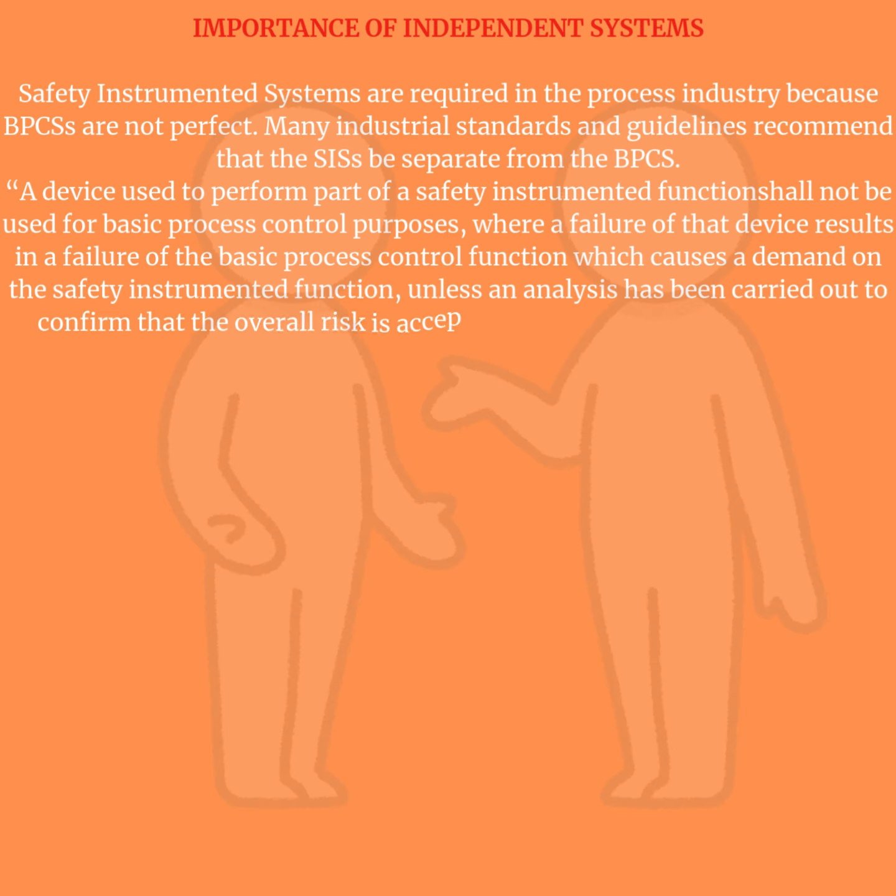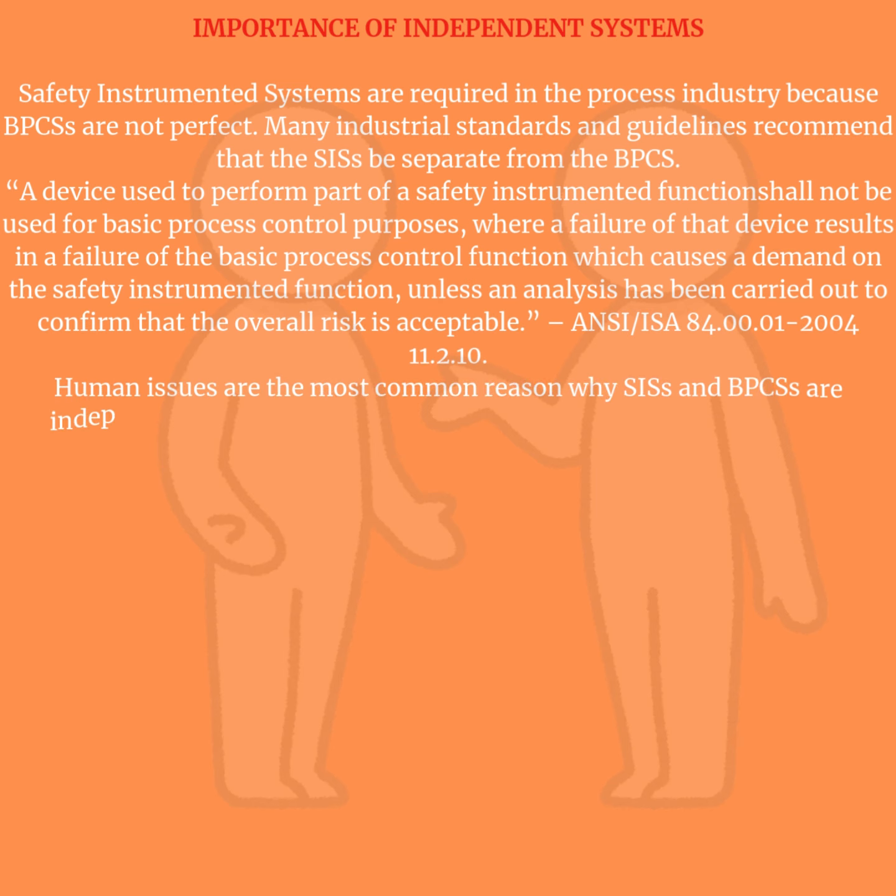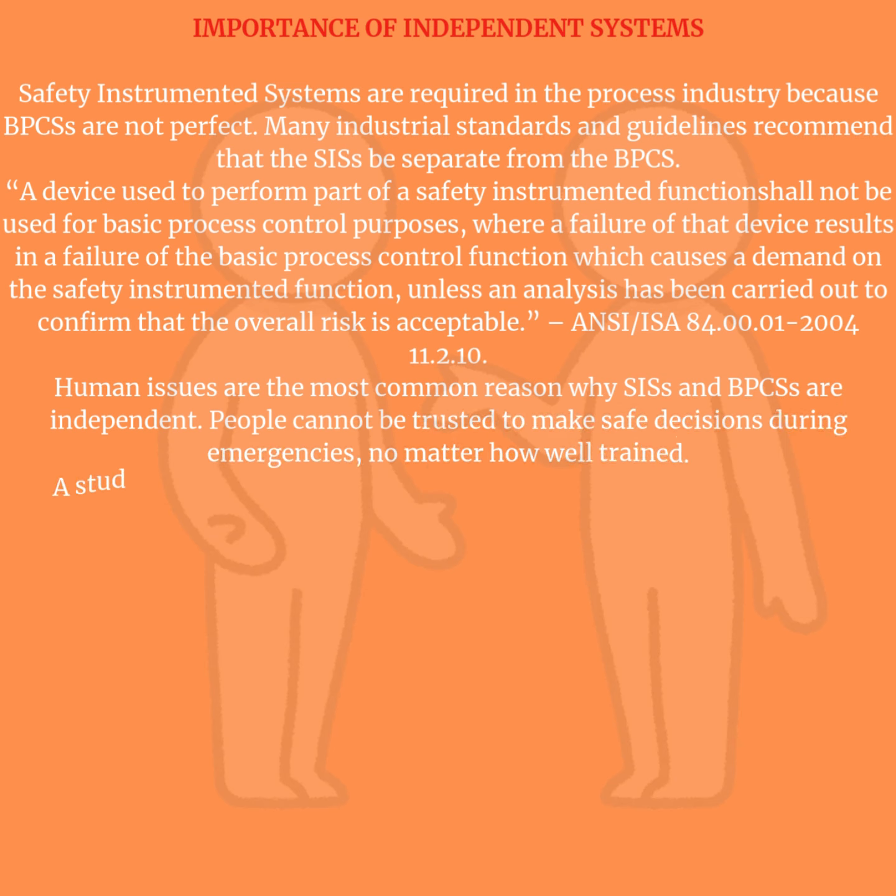ANSI/ISA 84.00.01-2004, 11.2.10. Human issues are the most common reason why SIS and BPCS are independent. People cannot be trusted to make safe decisions during emergencies, no matter how well trained.